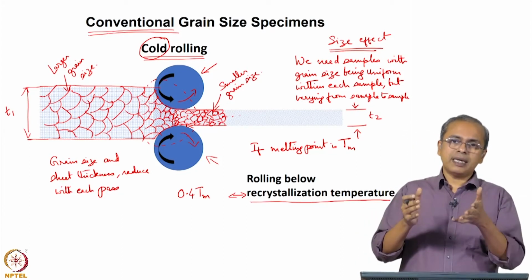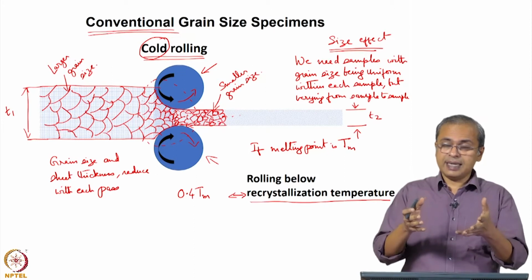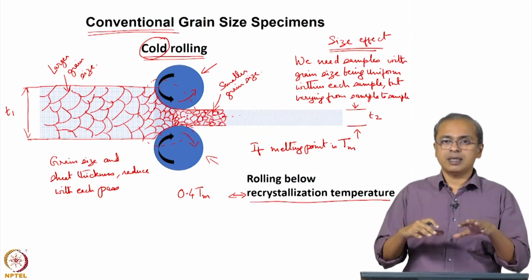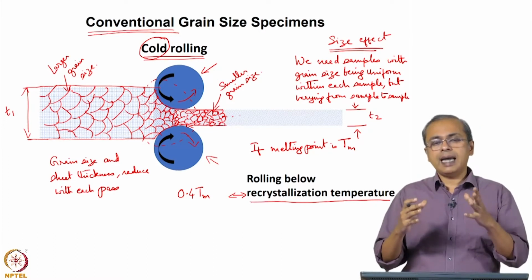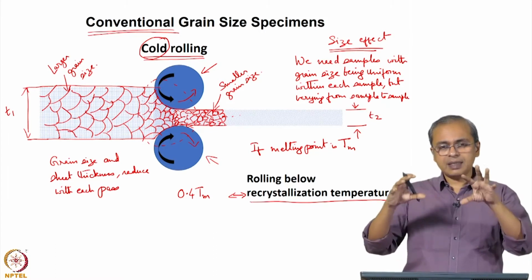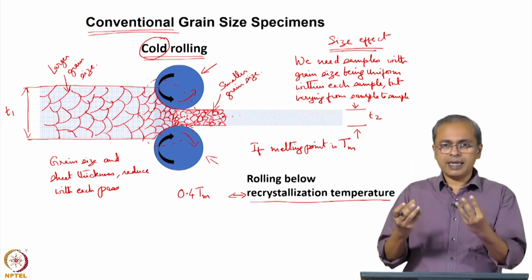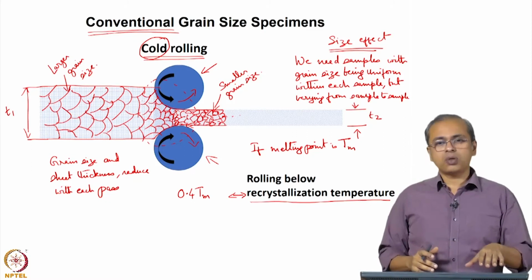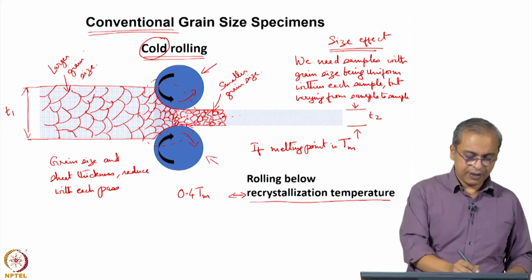So, if you have more grain boundaries, that is a higher energy state relative to crystal sizes which are large, which therefore have fewer grain boundaries compared to the volume, and if you take it to a high enough temperature, 3-4 of the smaller grains will coalesce, come together and form one larger grain. So, you will go back to the kind of grain structure that you have here.